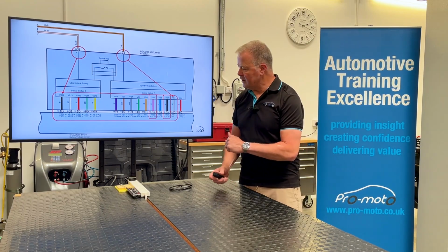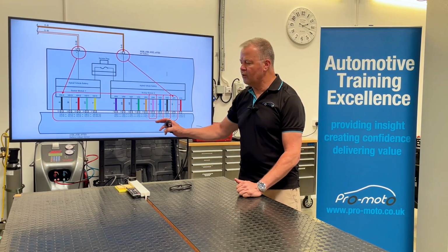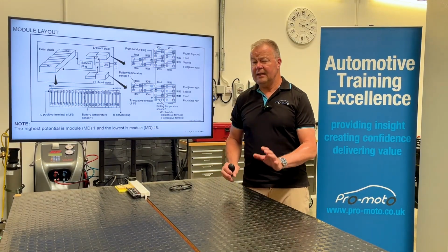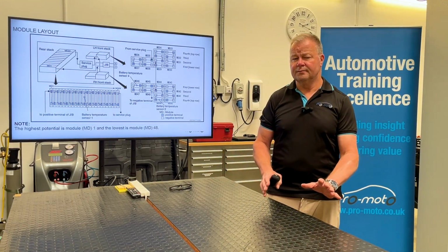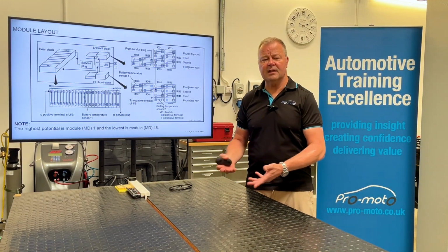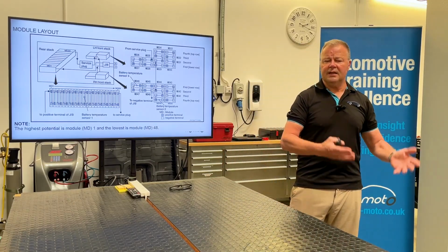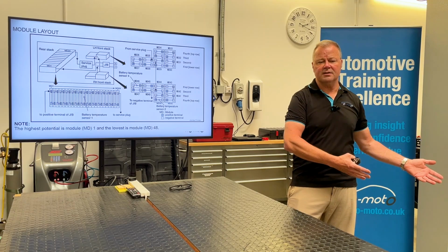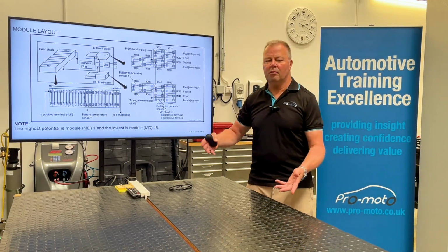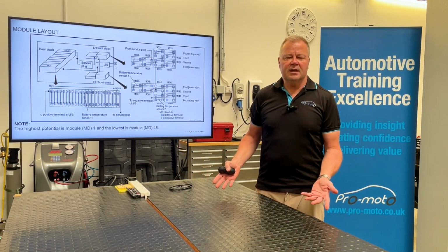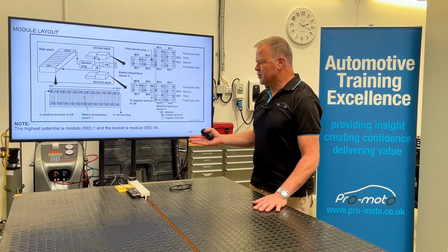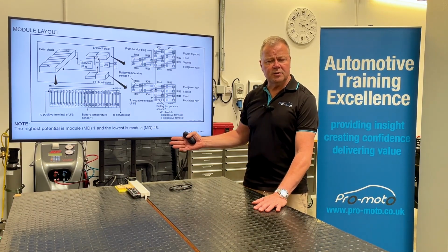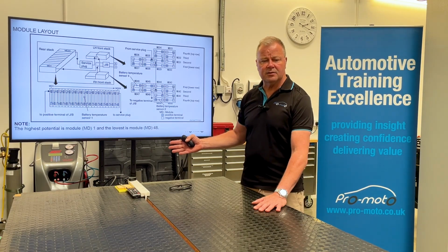Okay, so as you can see, this will be 2 and 4 is the biggest variance in the battery. Let's look at a Nissan Leaf then orientation. Now we would say, okay, if we got the same problem, maybe the negative end is where the modules start and the positive end is where the modules finish as far as numbering is concerned. So let's say we've got module 22, for example, this has 48 modules within the battery. So they're 2 cells per module, that gives us 96 cells in the battery.